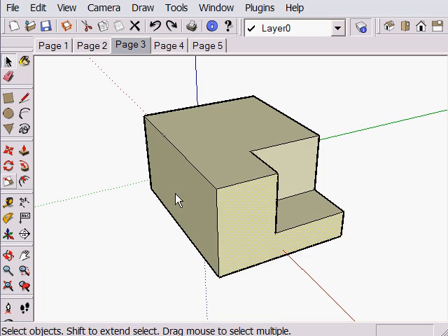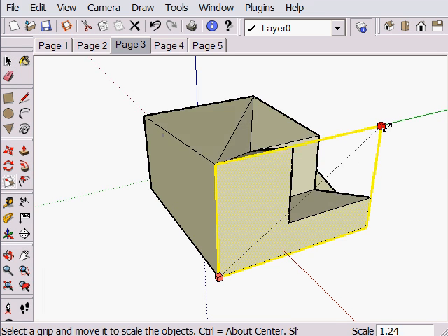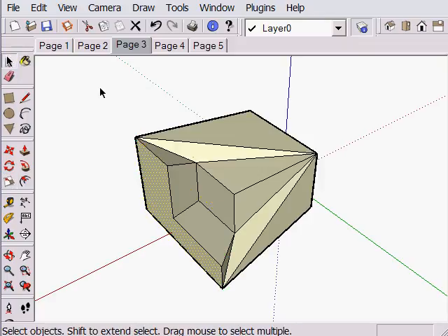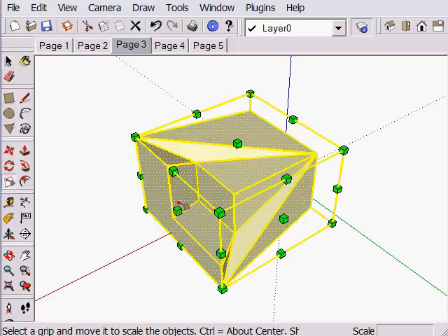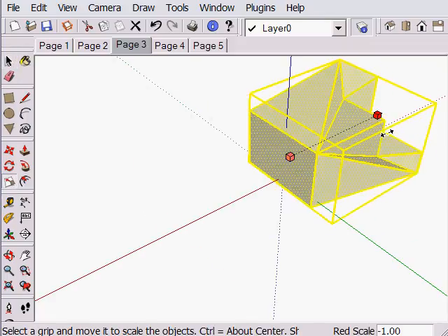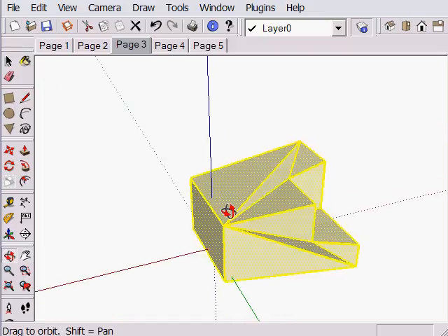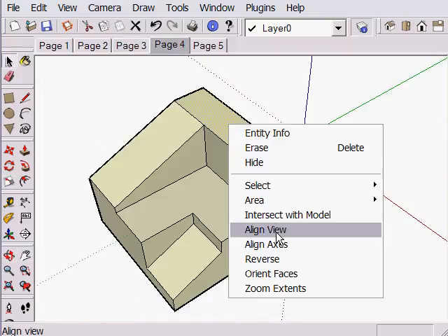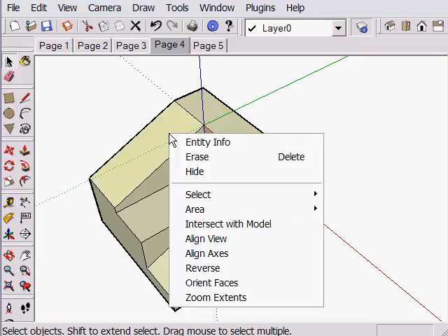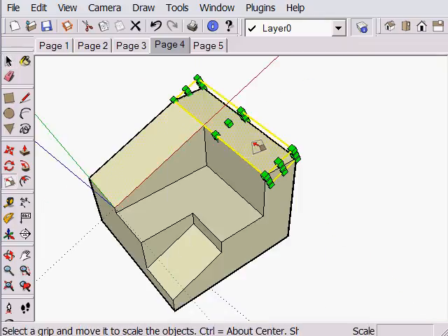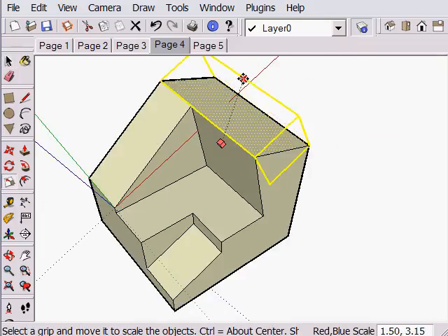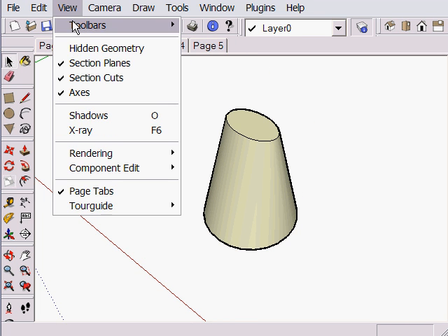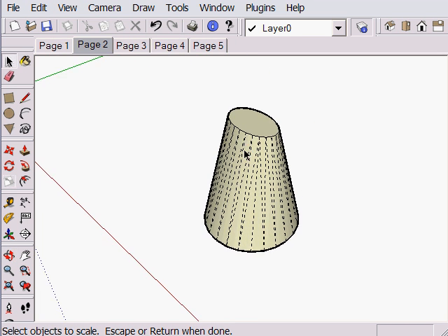Now for some fun. I can scale just one attached face to quickly reshape the volume. I can turn geometry inside out, creating a quick mirror of the geometry. I can scale a single face that is off-plane from the axis direction, and Scale treats the single face with the 3D scaling volume box. This process is great for creating warped volumes.